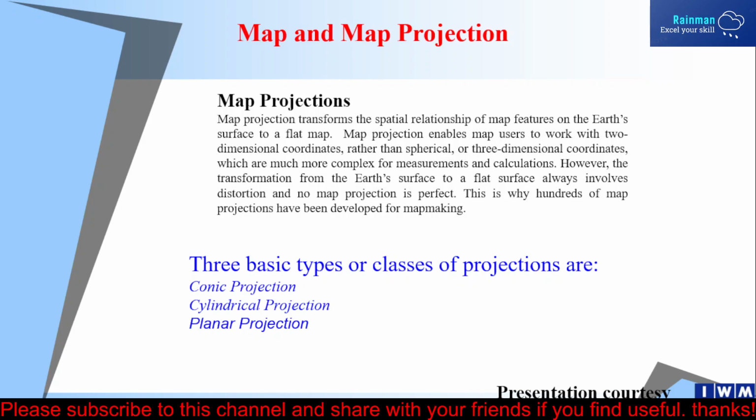When we produce a map in ArcGIS, we use different kinds of projection systems, like BTM, widely used in Bangladesh, which is referred to as Bangladesh Transverse Mercator. Another coordinate system is used by BIWTA, the Bangladesh Inland Water Transport Authority. They usually use BUTM, Bangladesh Universal Transverse Mercator.